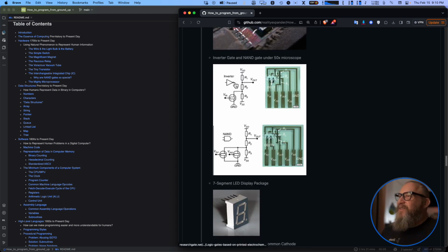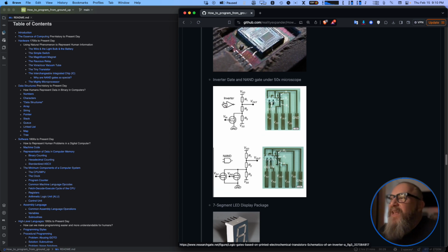And here's how the schematic would look. Here's the inverter, right there. The actual operation of the thing is right there. So it's V in, what's it called? VDD. That's where the power comes in. V out is this one, which is like, I hate these words. I wish they would just use 1 or 2 words, but they have to have all kinds of terminology. So this is input, output. Here's the input, here's the output, here's the VSS, which is just ground.